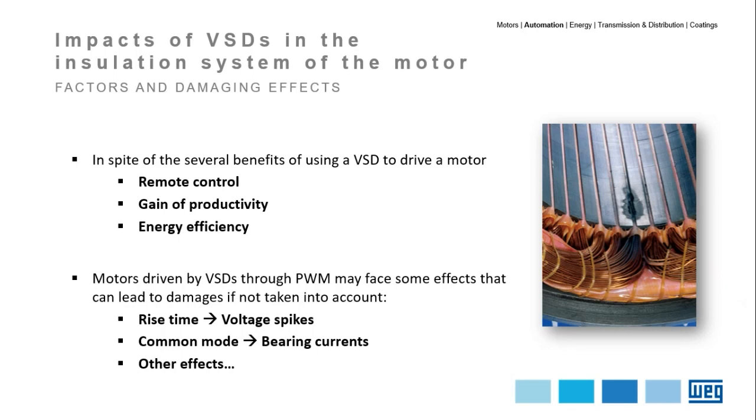Energy efficiency. The power system global efficiency depends not only on the motor but also on the control. Static inverters are high efficiency equipment, reaching typically 97% or more. Induction motors also present high efficiency levels, reaching up to 95% or even more in larger machines operating at rated conditions. When speed variation is required, the output changes in an optimized way, directly affecting the energy consumption and leading to high efficiency levels performed by the system. Inverter plus motor. Because of this advantage and many others, speed variation by frequency control is the most popular method that can be found these days.